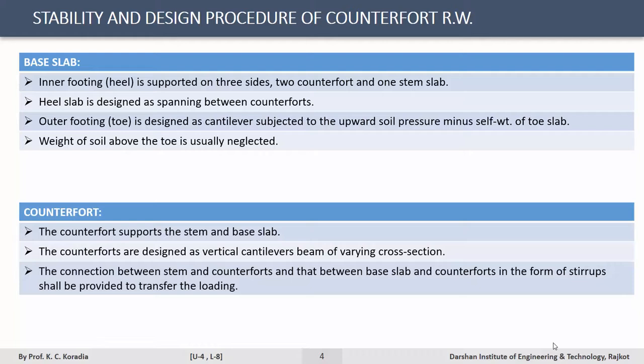Counterfort. The counterfort supports the stem and base slab. Counterforts are designed as vertical cantilever beams of varying cross section. The connection between stem and counterfort, and that between the base slab and counterfort, in the form of stirrups shall be provided to transfer the load.